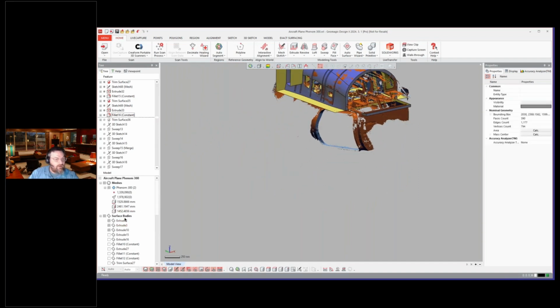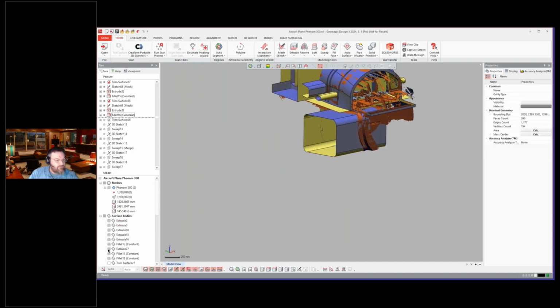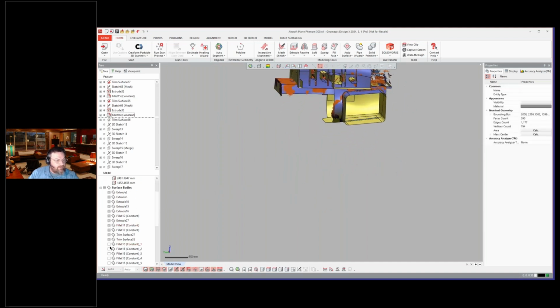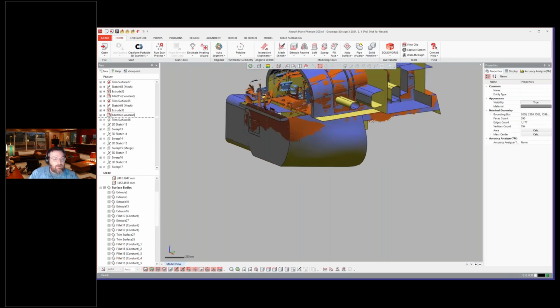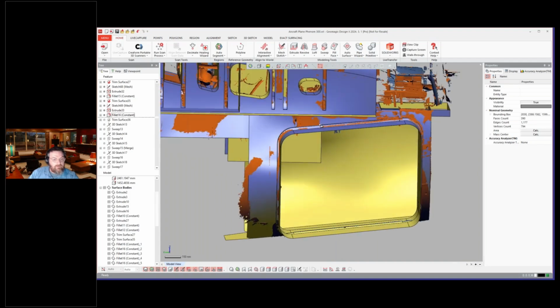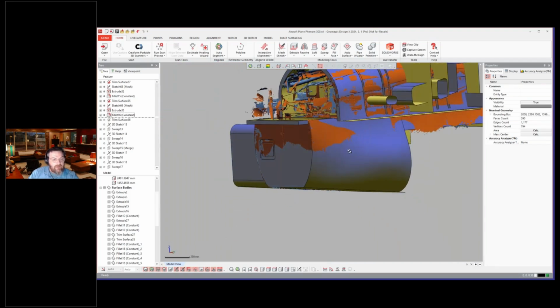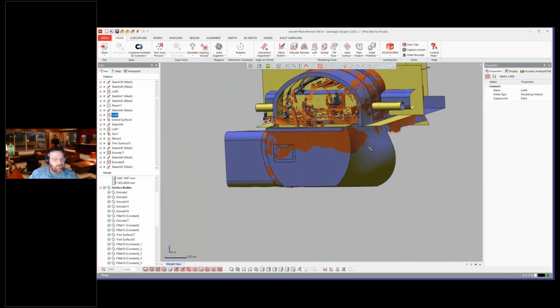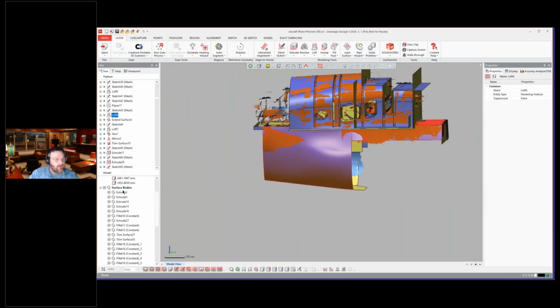You see here's all the extra pieces here for cutting the windows and everything. All the different pieces. Really cool. And this was the loft wizard on the side. And then mirrored across, you see here, it's a surface loft on this side first, and then mirrored across. And then trim everything in, trim, trim, trim.